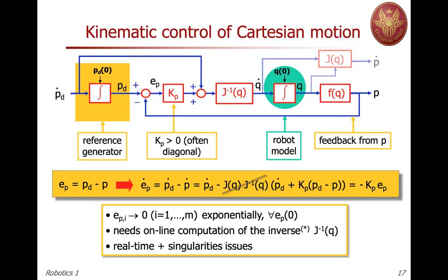We activate, monitoring the least singular value of the Jacobian, so a distance from the singularity, if you wish. The determinant, but we have already commented why the determinant is not a good measure of distance to a singularity, although it goes to 0 when the Jacobian is singular.